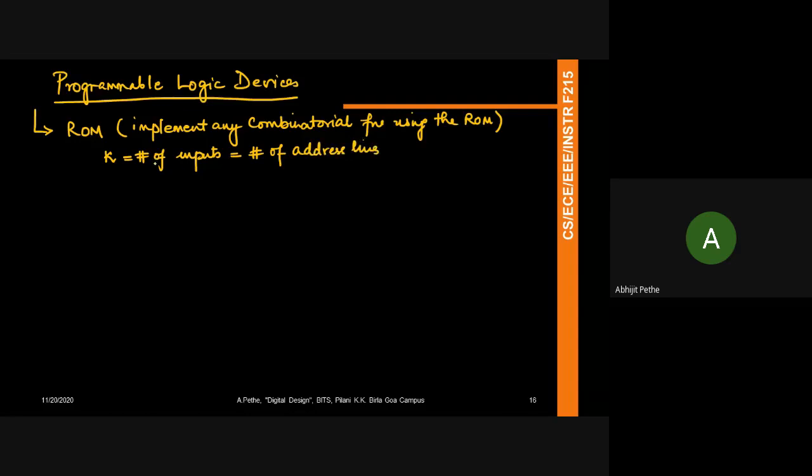So what the decoder is doing is essentially, remember the ROM is made up of a decoder and a memory. The decoder is nothing but generating the minterms. Once the minterms are generated for the various input combinations, that particular combination of the input can give you a multi-output variable. So a ROM doesn't make sense if you have only one output you want to generate, because essentially your ROM will have this value of 0 or 1. But suppose you have to generate multiple outputs made up of multiple inputs, then a ROM is a one-shot solution to get you that.